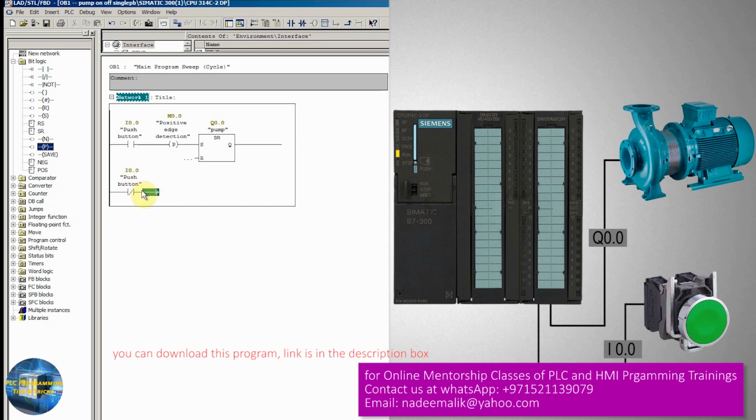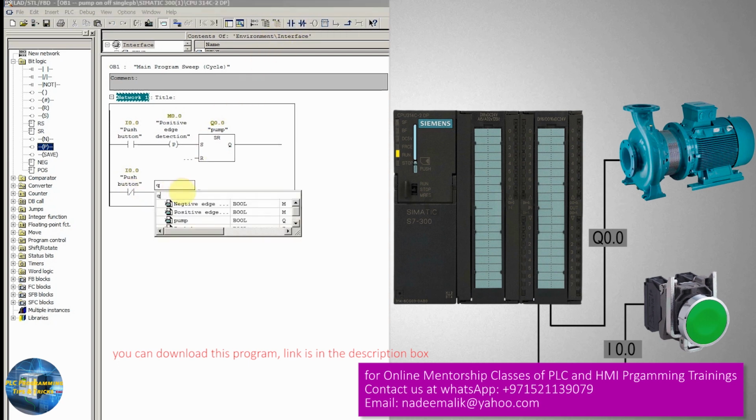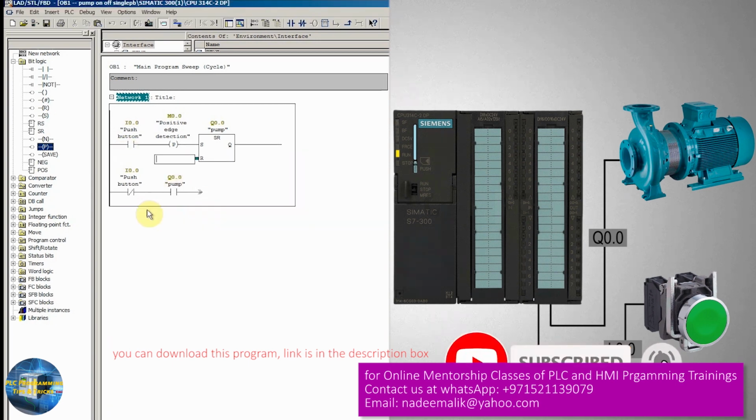So we will insert a normal open contact of Q0.0. You can see here that once our output Q0.0 is high, this normal open contact will be closed. And as we have already released the push button, this normal close contact is also closed now.